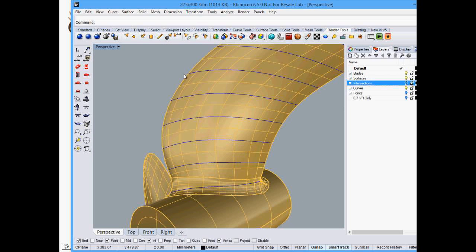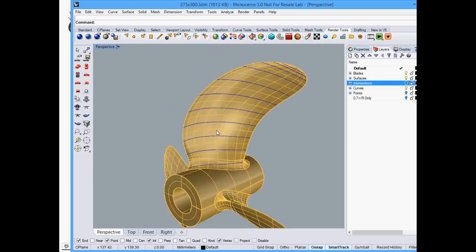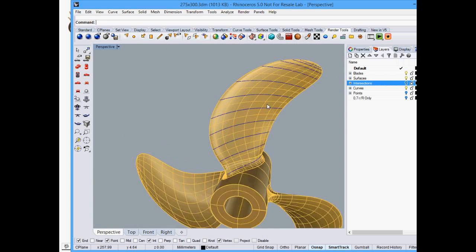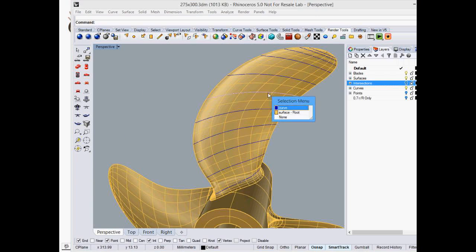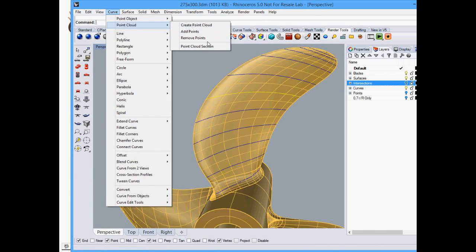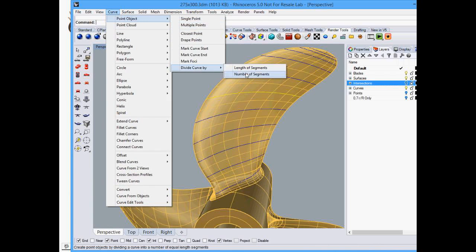This is the path that an inspection probe would move across as it sweeps from the leading edge to the trailing edge. So we're just mimicking those paths, and we're laying those out on our propeller blade. What we do with this curve is we can take it and prepare points on the curve, and then we can use these points as input into Scan Converter.